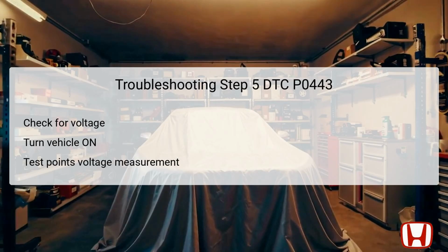This measurement is critical. A positive voltage reading suggests that the wiring is intact, but may also indicate issues further down the line. Conversely, if battery voltage is absent, it indicates an open circuit in the wiring connecting to the number A37 fuse. Repairing this open circuit should then be the subsequent action. Understanding the voltage readings can provide crucial insights into the electrical health of the system.